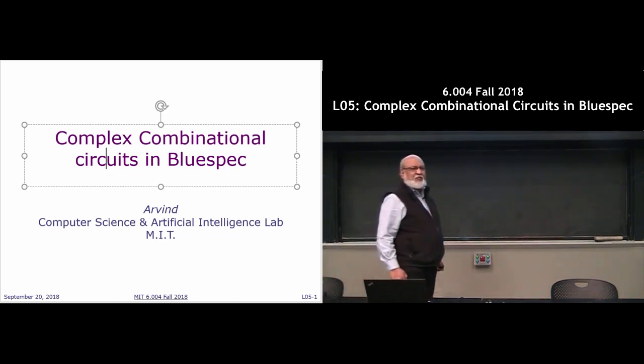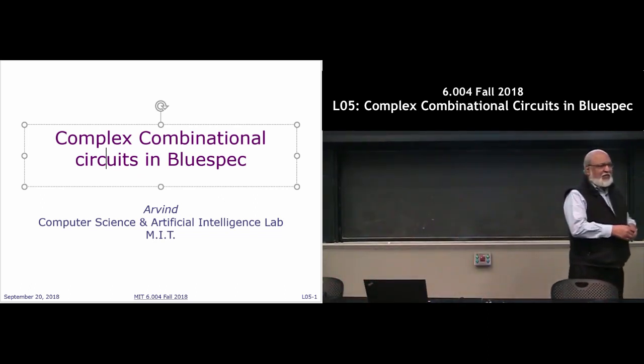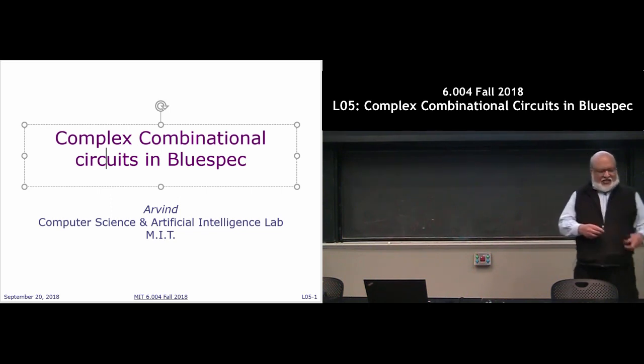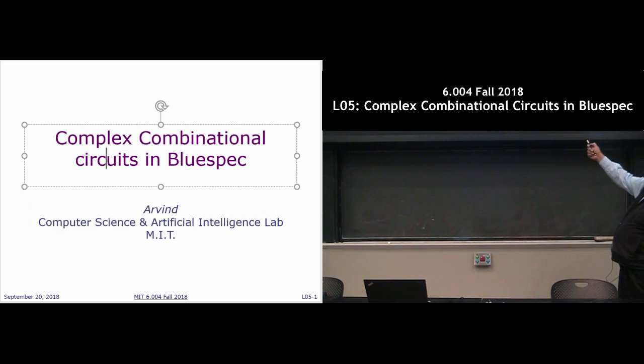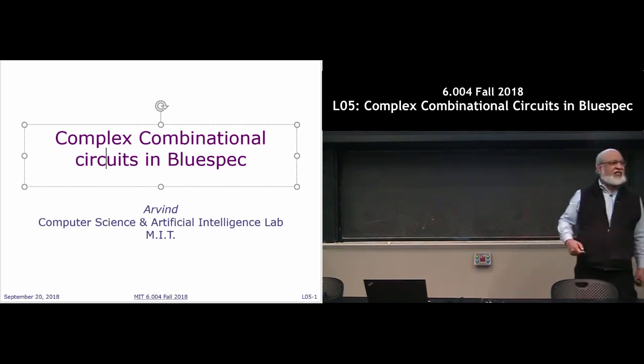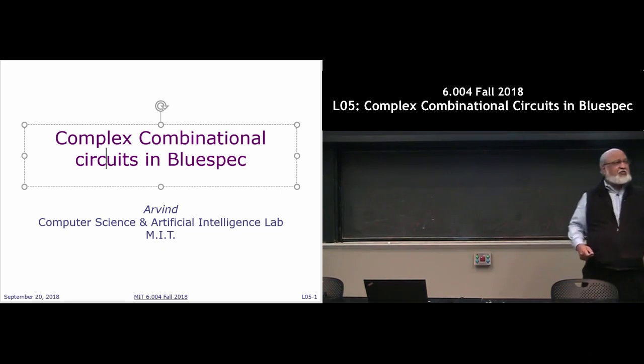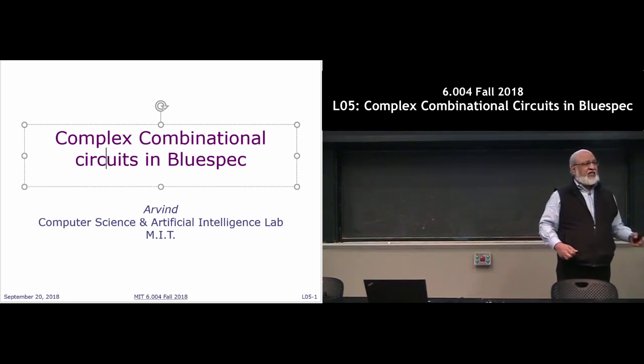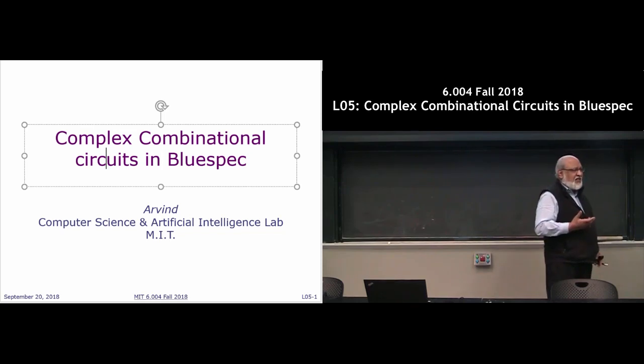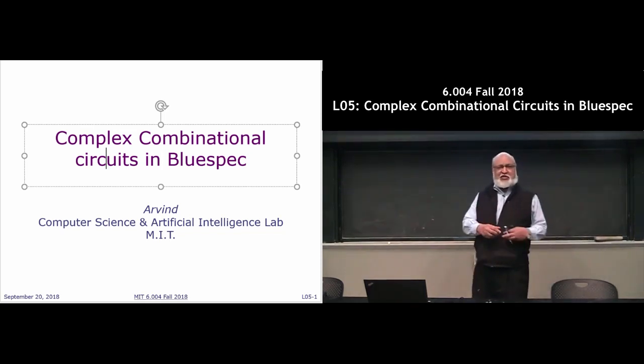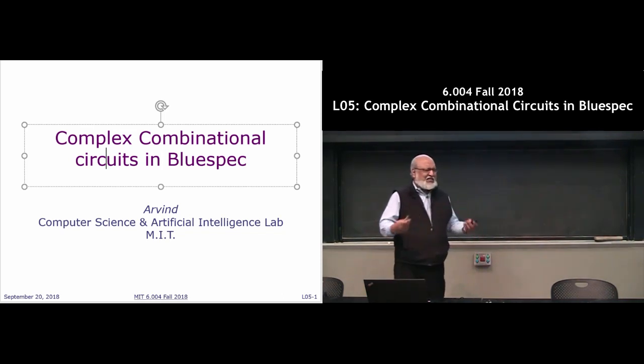Yep. How is that different from what you said? I thought he meant dynamically you can quiz how big x and y are. You can never quiz, right? It's declared here that this x is 3 bits wide. Therefore, this x also must be 3 bits wide. There is no possibility in hardware or even in software to actually ask the question, how big is x? It's like instantiation of variables. Should I move ahead?